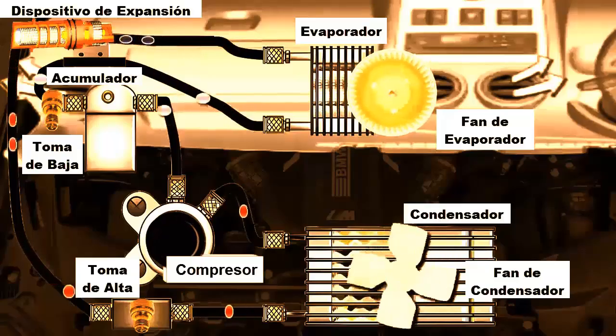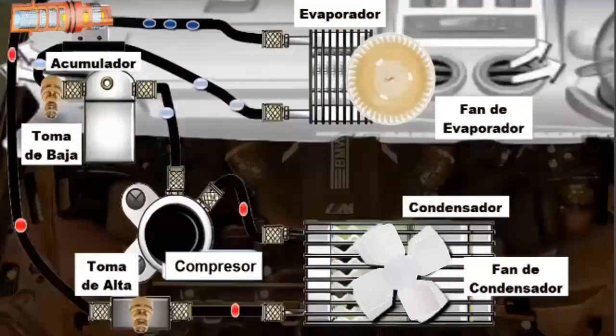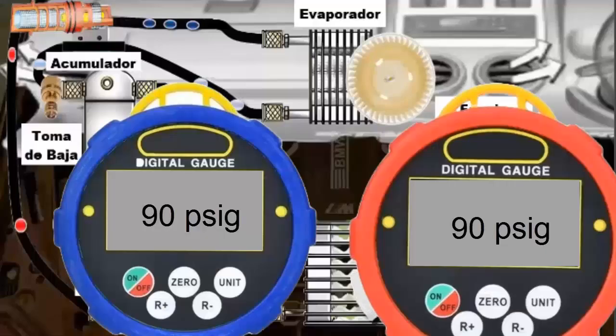1. Air conditioning off. In this case, regardless of the engine speed, the pressures on both the high and low sides remain practically the same. This happens because, whether the vehicle is stationary or in motion, the compressor is off. Here, the high and low pressure gauges should show the same value. For our R134a refrigerant, these pressures equalize at around 90 pounds per square inch, psi.